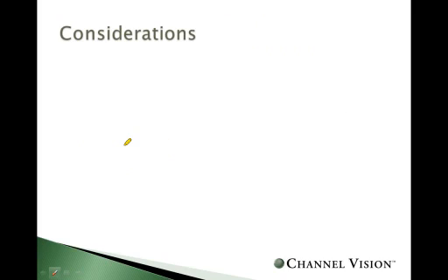Some additional things for you to consider when you're designing a system or have a customer with an application where they want to see their cameras on their TVs, the first question you're going to have to ask is, how many sources do they have? How many cameras, or are they feeding this to a DVR? And this question will give you the answer to what modulator to select. Just as a reminder, we select between 1, 2, 3, and 4 inputs, but we can combine up to 8 modulated inputs into the cable signal to the cable combiner.